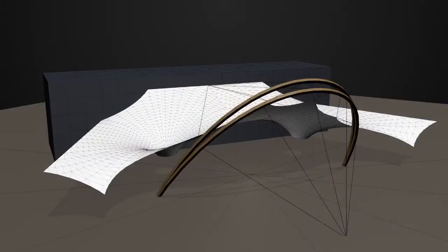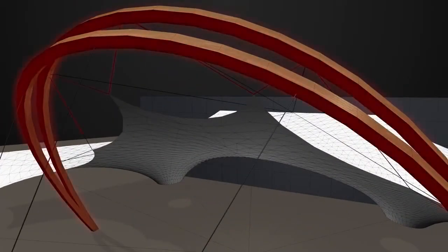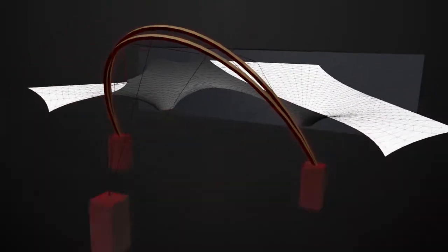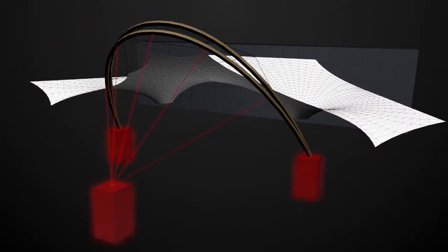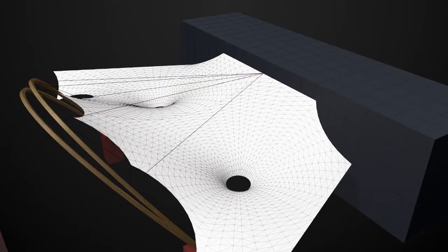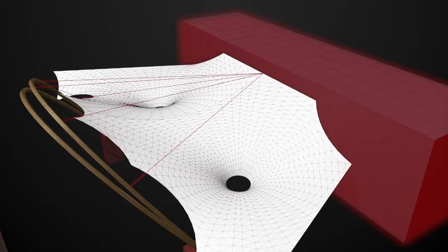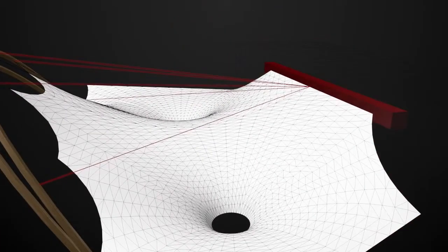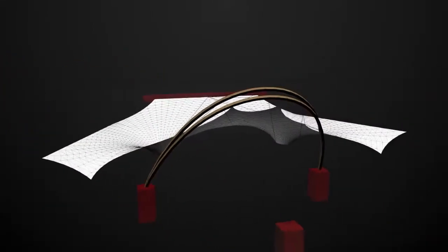Canopies can contain their tensile loads within their own structural framework, transferring the load into concrete foundations or ground anchors. Or they can transfer their loads onto an existing structure. However, the large lateral loads often require the structure to be reinforced.